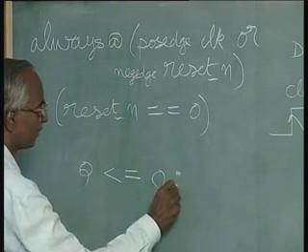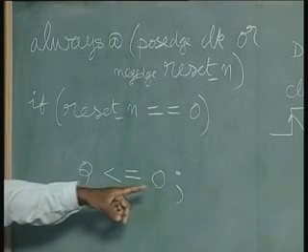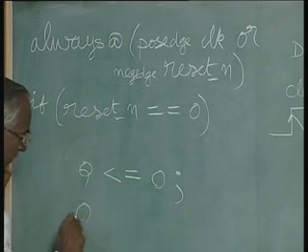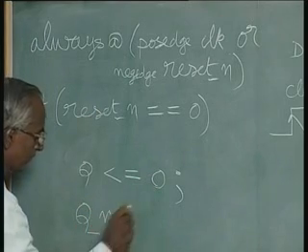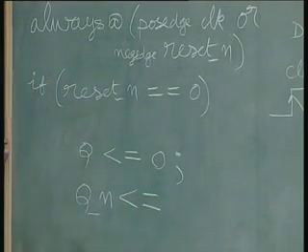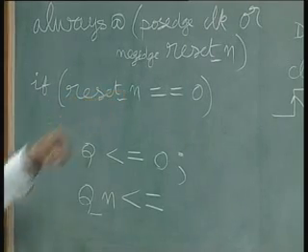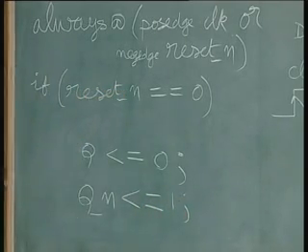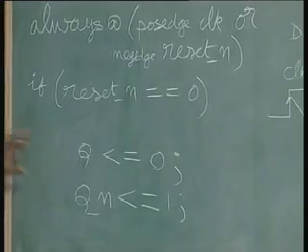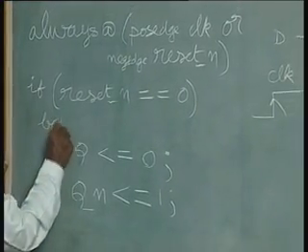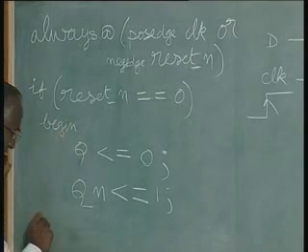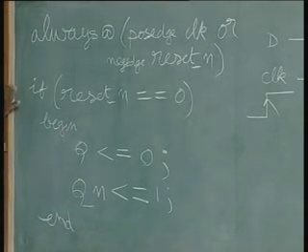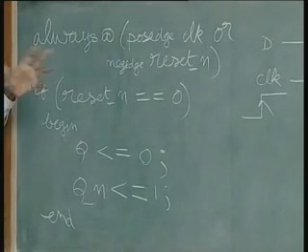Here one statement is complete, therefore a semicolon as in C. Then we can write the next output also. Here what we want is 1 to come there, so we will just put 1. Because it is more than one statement, we put a begin, end. So this completes the resetting of the flip-flop.